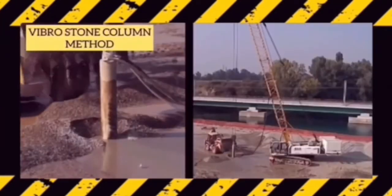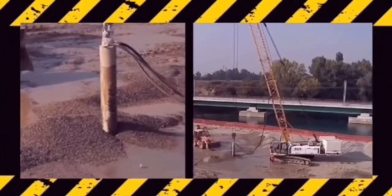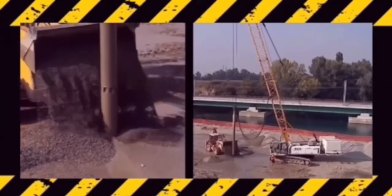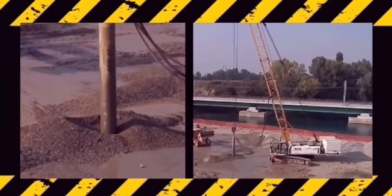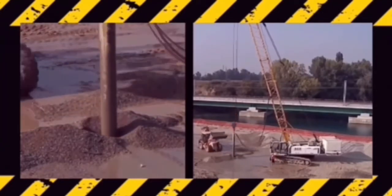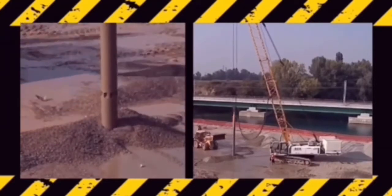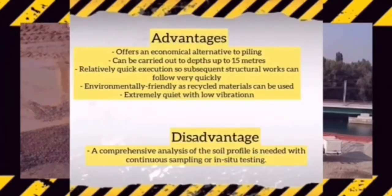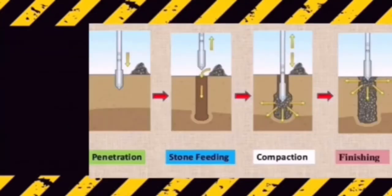The first technique of ground improvement is the vibro stone column method. Vibro replacement stone column is a ground improvement technique to improve load bearing capacity and reduce settlement of the soil. The stone column consists of crushed coarse aggregate of various sizes. Vibro replacement is the process of constructing stone columns using a vibratory probe. After the probe penetrates to the depth of treatment, stone is filled into the hole from the ground surface to the tip of the probe. This method offers an economical alternative to piling and can be carried out to a depth of up to 15 meters, but a comprehensive analysis of the soil profile is needed with continuous sampling or in situ testing.